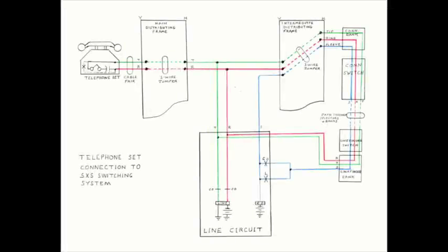Before we get into the ringing process, let's take a quick look at what would happen on a call to an unassigned telephone number. If the called number is not in service, there will be no IDF cross connection to a line circuit. If the IDF tip, ring and sleeve terminals are just left unconnected, the sleeve bank terminal would be electrically dead, since there would be neither battery nor ground provided from a line circuit.